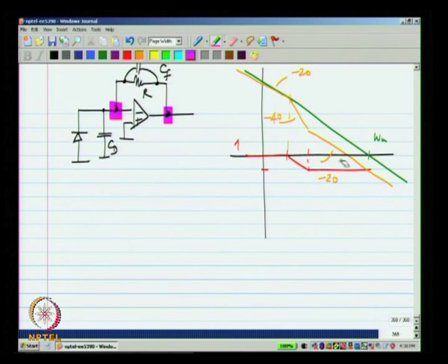omega u. Okay. Now, this is an interesting example where by using a 0 we introduce a phase lead or a reduced delay and make the circuit stable, and also the bonus that we get for the transimpedance amplifier is that when you are given a diode capacitance CD and a resistance R, you can still increase the bandwidth by using a faster op amp by using appropriate CF. Remember, this was not possible with either of the two circuits by connecting a resistor directly across the photodiode or by using a transimpedance amplifier.